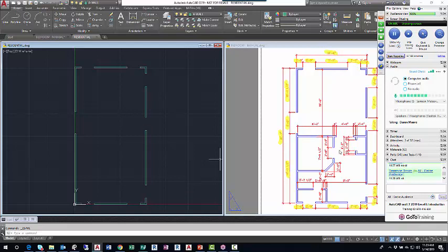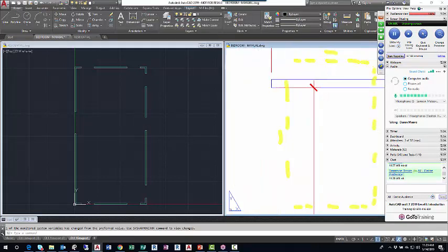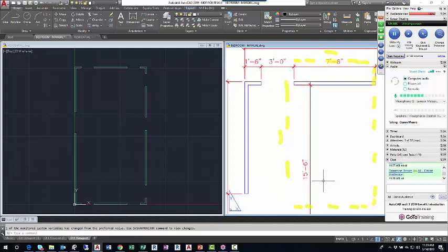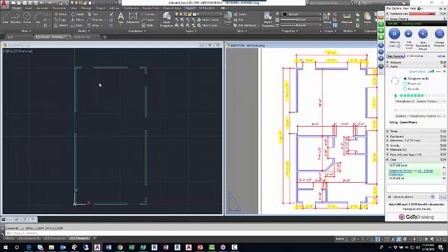In plan view, this 4-foot opening could be an arch, it could be a doorway. It certainly terminates at a ceiling that we can't see. So I'm going to use the offset command, and I'll zoom in. The bottom line of the 2 top lines, I'll use the bottom one. I'm going to offset it down the screen 15 feet 6. So I'll go offset 15 feet 6, enter, left click this bottom horizontal line, move down, and left click.